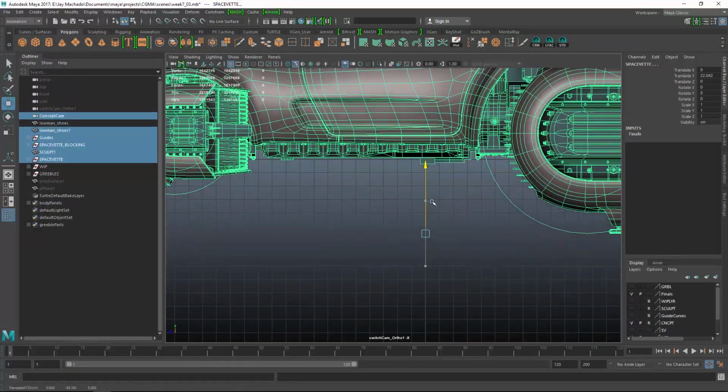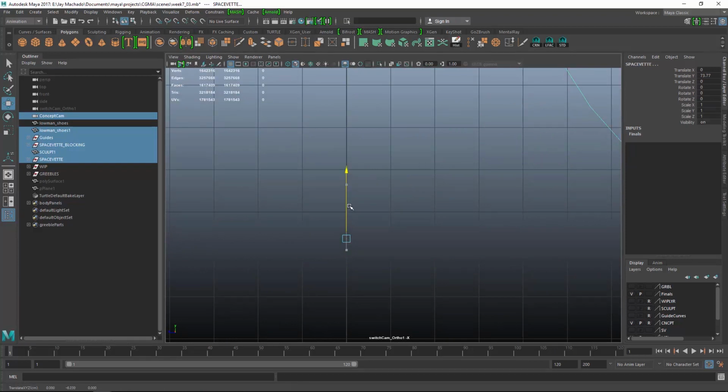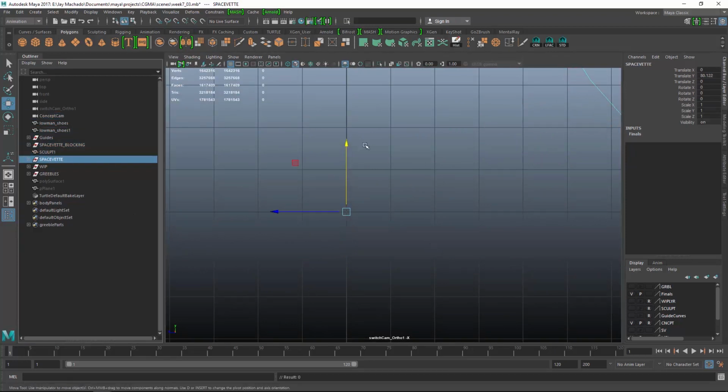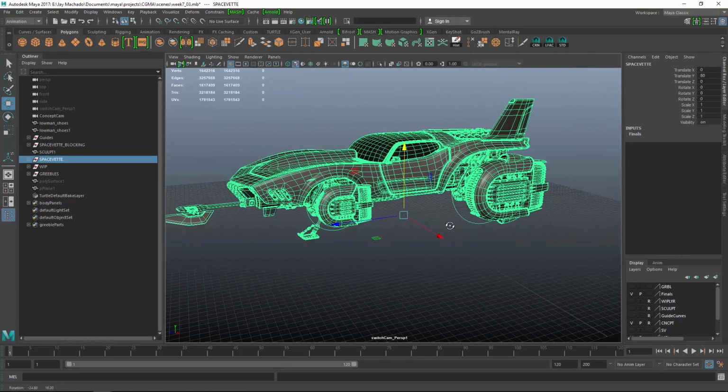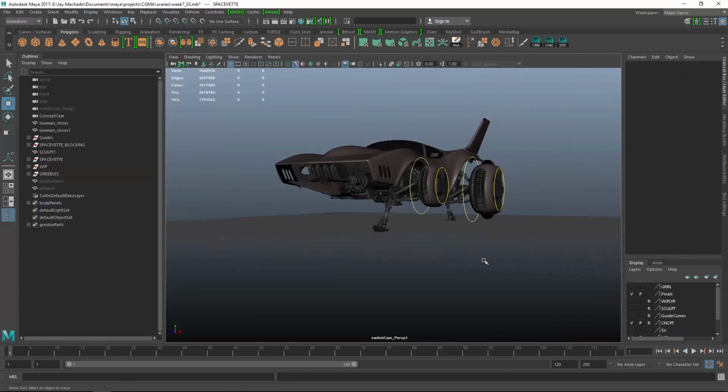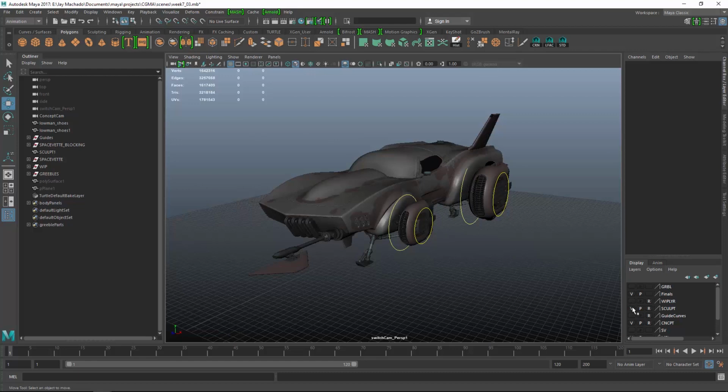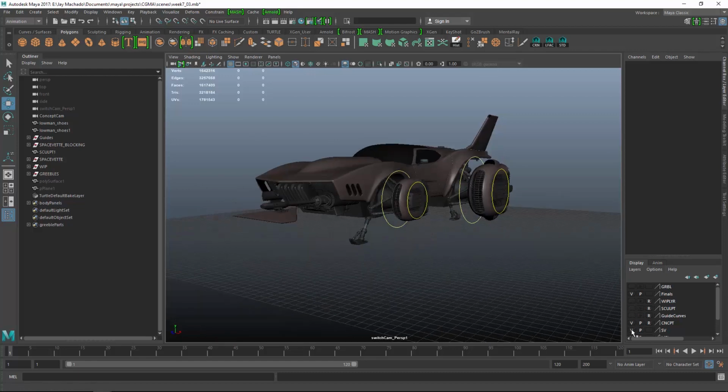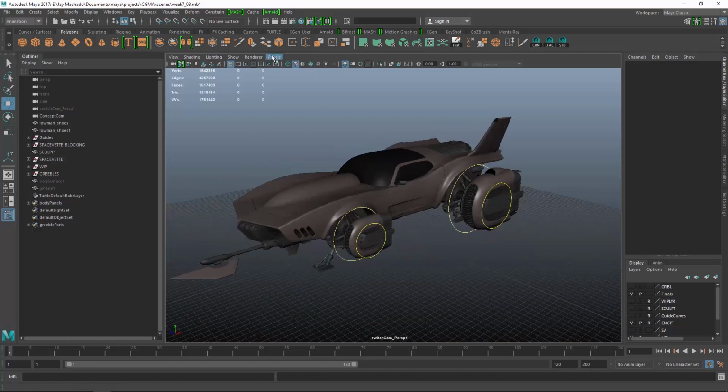So I'm going to just eyeball that up to the origin, but I only want to snap the space vet null to the origin, because if I snapped everything, all their pivots are in different spots and they would all just snap to wherever their pivot is to the origin. So the only one that I really cared about being precisely at the origin is the space vet null, so that's the only one that I did.